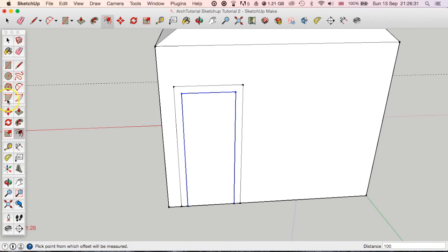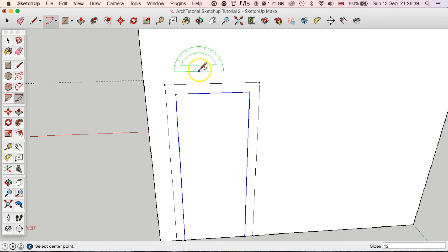You can see on the left hand side here you've got a few different options. You can see the arc here. By selecting that, you can see it creates half a compass shape. So first of all we're going to snap onto here, hover over for just a moment, scale up, and then click, and then to the other side until it snaps in place.